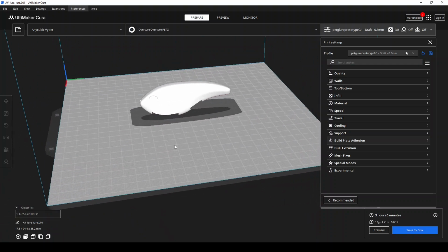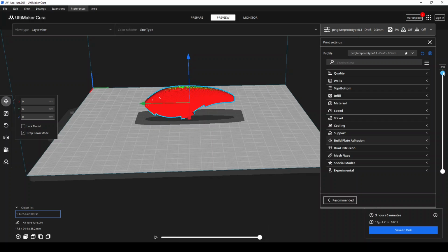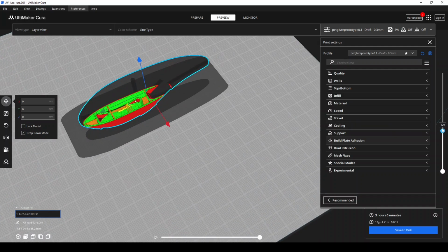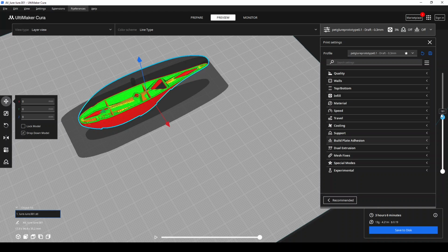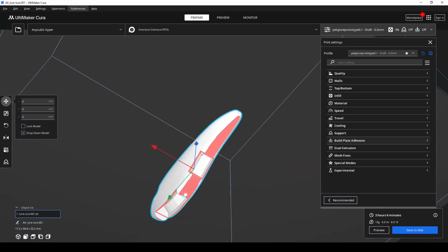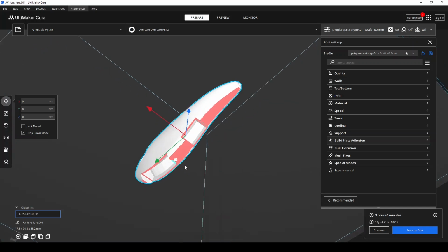Now we've got it sliced. Obviously, you get here, you've got an island, and printing under there, it's going to want to probably put supports for that, for sure. Everything in Cura, everything in red is going to be supported. So you're going to want to put supports here and here, these flat spaces along the rim of the little cutout we made.